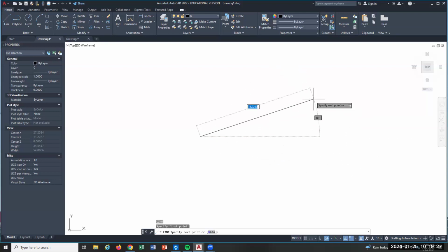And you'll see I have what's called a dynamic input going on. And it's highlighted, meaning anytime AutoCAD highlights something, it's ready to go. That box is ready. You don't have to click on it. You don't have to choose it. If I typed right now, it'll just go into that box. Okay, so this would draw a line 25 units long, inches, because I'm in inches, at 18 degrees. Aiming, distance, hit enter, boom, shoots it.